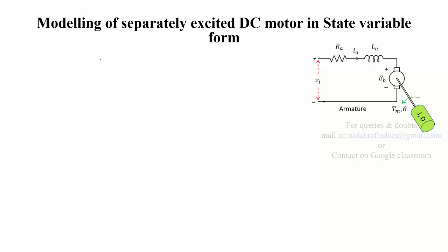First of all, you will have to identify how many state variables the system has. For electrical systems, one reference book mentioned that you will always look for the number of energy storing elements in order to know the state variables. This is always true, and you will adhere to it instead of thinking of the differential equation.